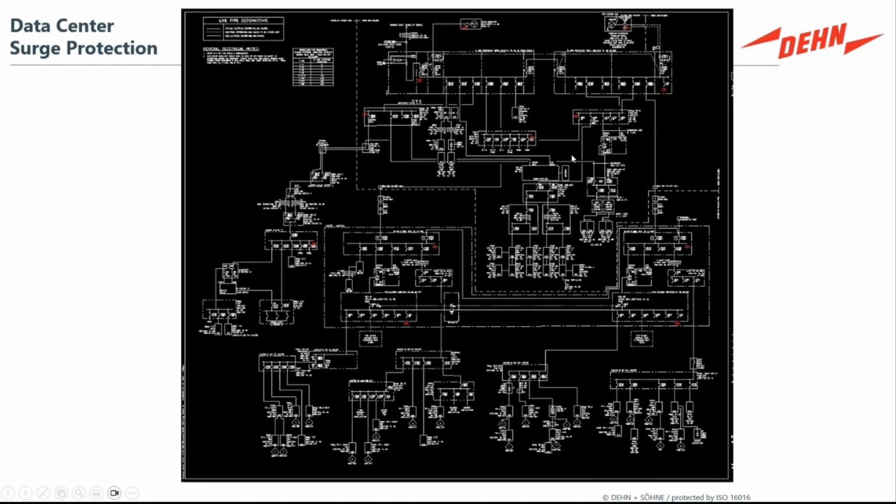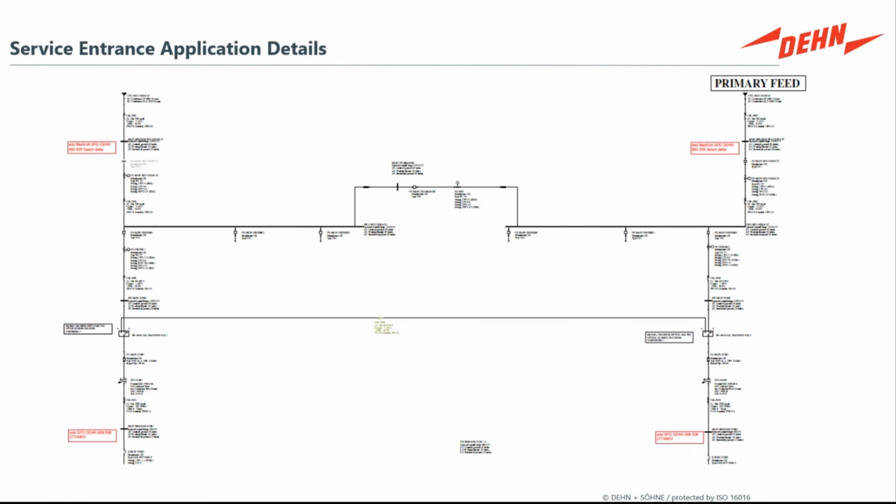These are what would be considered electrically very complex. And so what's going to be extremely important is to ground and bond those systems adequately. And what we're finding is these systems are having additional resources applied. These data centers may not have started out as a data center. It might have been an office building that's being converted in a metropolitan area. And now you're bringing in additional generators and backup transfer switches, battery systems, rooftop mounted solar systems, solar photovoltaic systems. And all of these multiple sources are not necessarily bonded adequately.